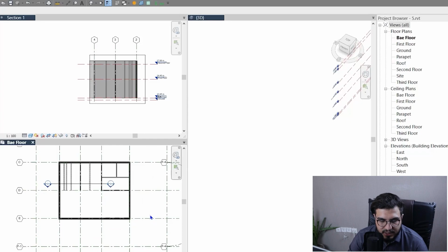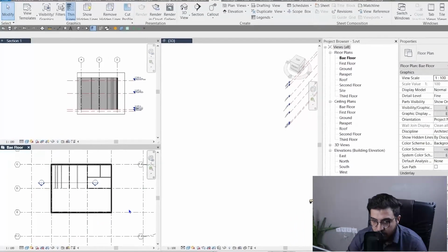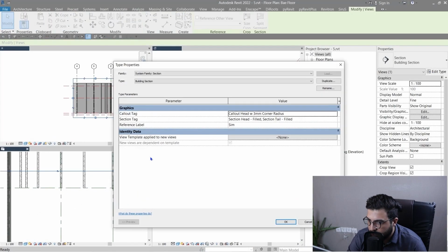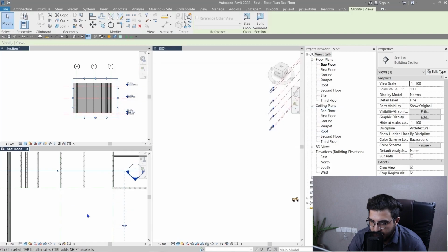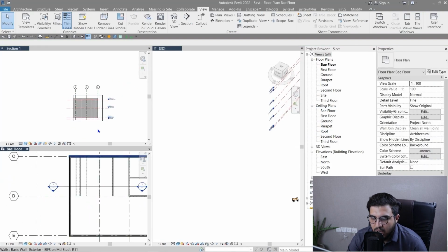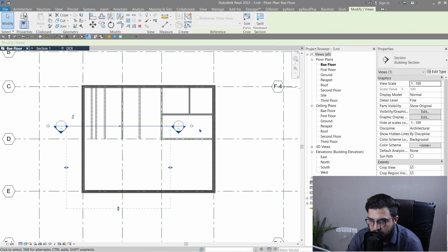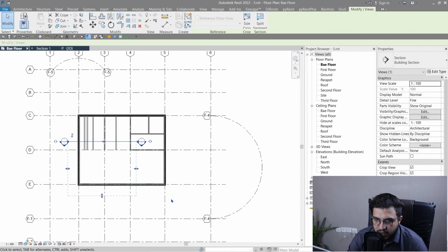And that was it for the section part, and this is a beginner part for section, so I'm not going to go into details. You will have some options in edit type for section, the tag of it and the shape of the section tag, and the other options are not that functional, so I'm not going to go into detail in here. Let's press TW in here to go to the full screen mode. Let's delete this one, or we can let it be in here.